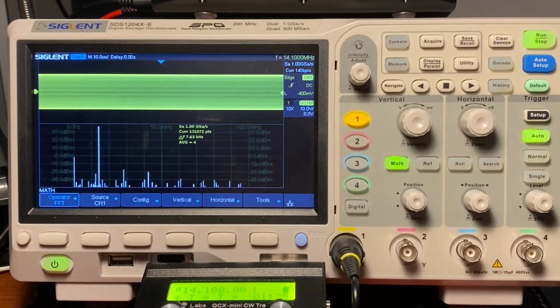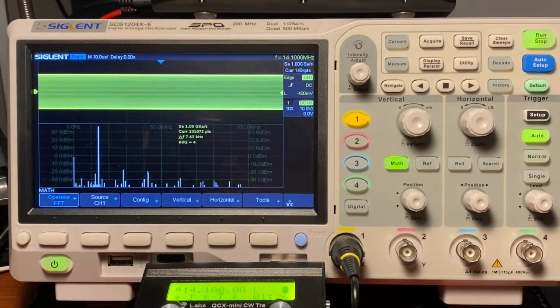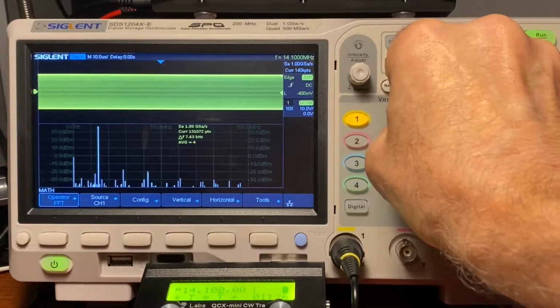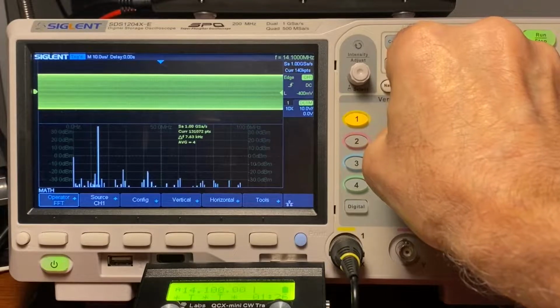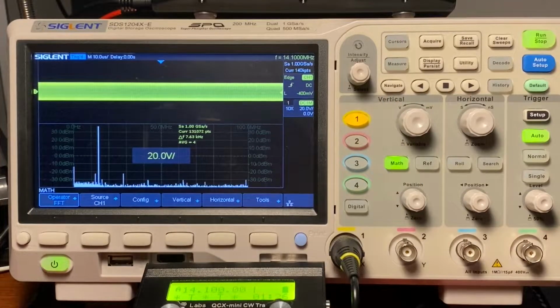It's very important to then set the input channel's analog gain to avoid clipping or other forms of distortion or loss of dynamic range. I usually get maximum linearity when the signal is occupying about 1/3 of the display area. So it's now occupying 1/3 of the analog span on the display.